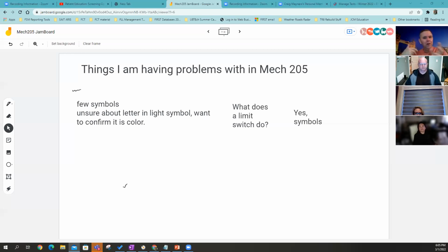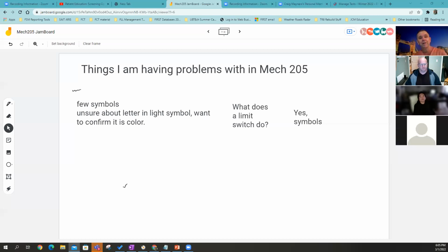Then you have to look for all of the outputs that are required, right? Things like motors and lamps and alarms and those things. You have to define all the outputs. Then you have to look at all the inputs that he's asked for, things like switches and limit switches and sensors. All those input devices have to be clearly defined and named. And then we do a Boolean equation that defines the relationship between the outputs and the inputs, right? And from the Boolean, we would take that to a control system. We'd actually build our ladder diagram from that Boolean expression.